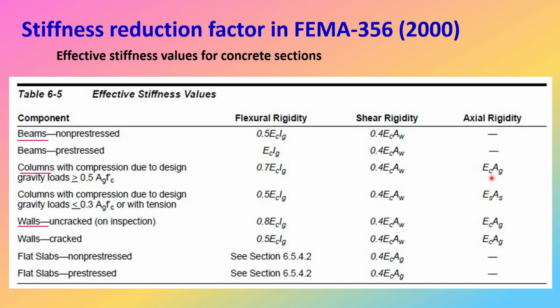Here EA is coming into picture. So the full thing is considered, because the axial force is compressive force, no tension, so no reduction here. So note that here the cracked section, as per the nomenclature of concrete, indicating absence or presence of tension, is reflected here. But actual crack or damage is reflected in the case of shear wall as given here.